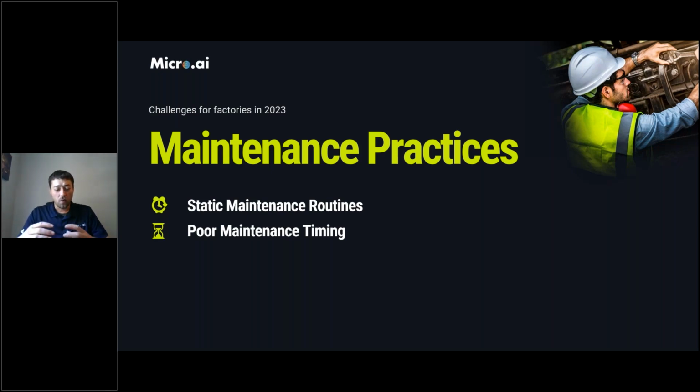Well, without the insights and without the visibility, these maintenance timings could end up being too soon to where you miss a problem that wasn't quite showing itself yet, or they could be too late where you get there and now instead of being just a slight problem where we may need to change a bearing or a consumable, now it's caused wear and tear to other parts of the machinery, and you're now replacing more expensive pieces of equipment because you weren't there on time or you were there too late.